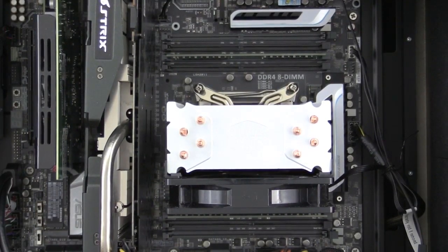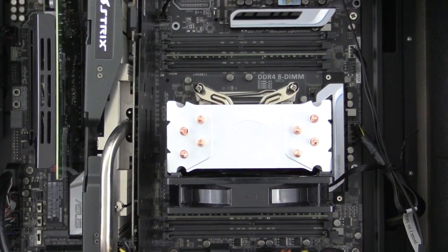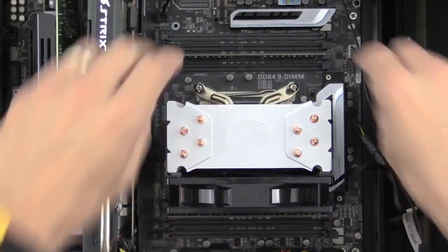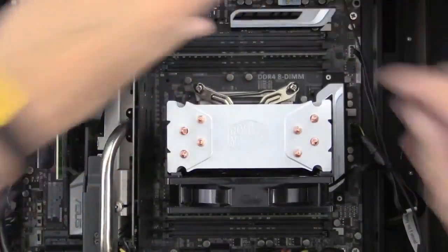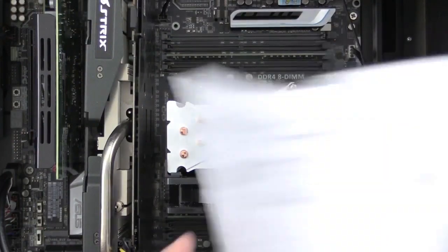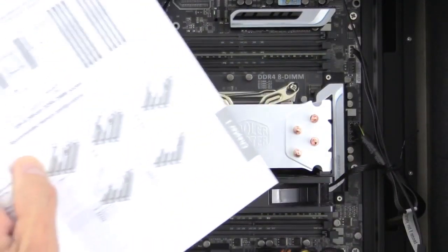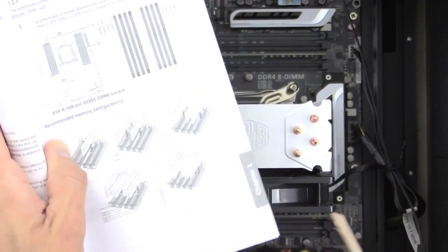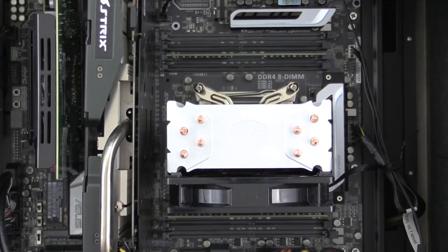And so what we need to do now is just check, make sure there's no contact showing, make sure it's indeed pressed all the way down, both of those, and double check the slots. We want to make sure that we are installing to the correct location, and that's in your motherboard documentation. And I'm looking at that now, and it does look good, B1 and D1.